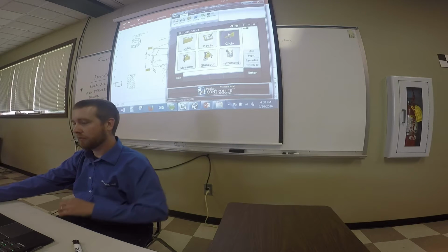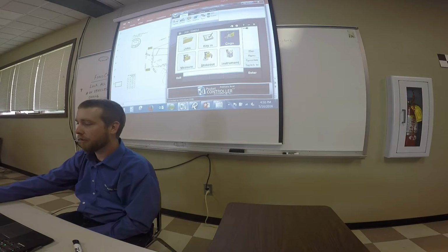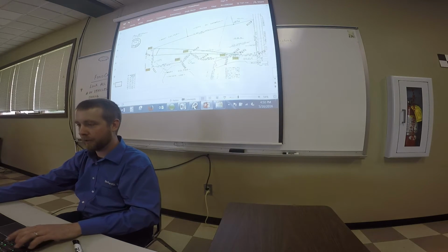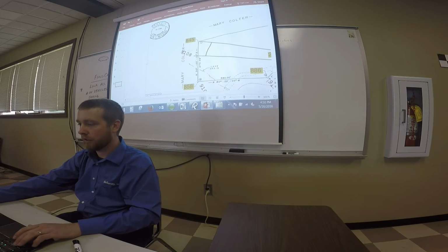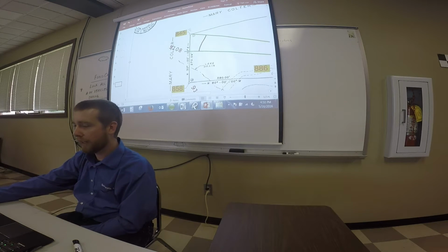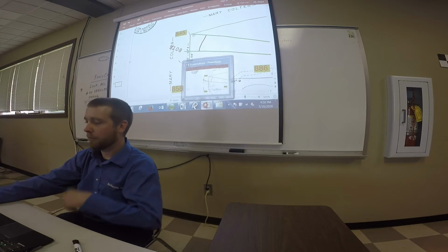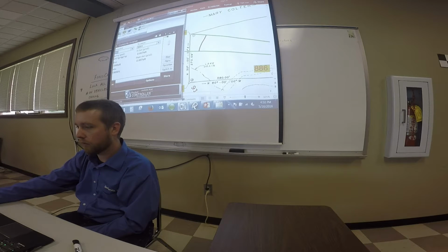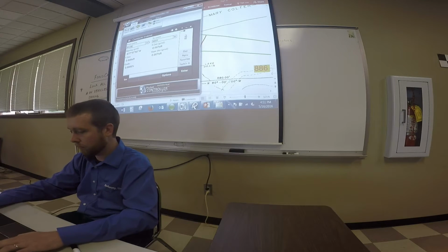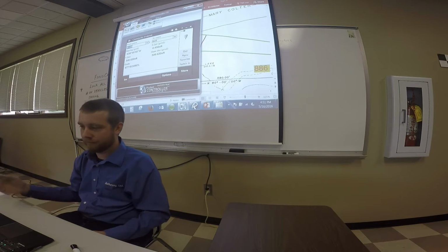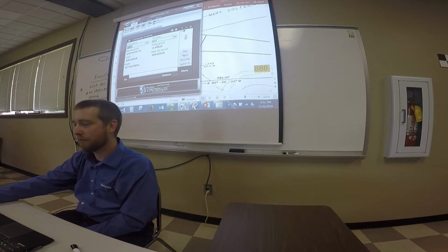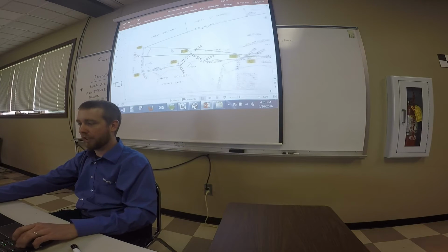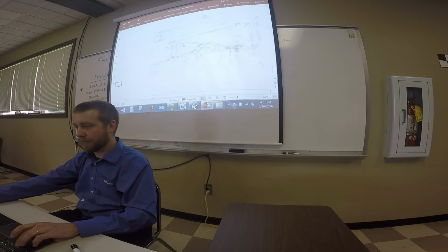Okay, so now we've rotated our points. Now we're going to check our rotation. Go to COGO, go to inverse, and we're going to inverse between 9108 and 845. We'll see if that rotated properly. And 4/10. That's our rotation. We've rotated in. Now we're locked onto the site within 4/10. We can go around and we can look for pins as needed.